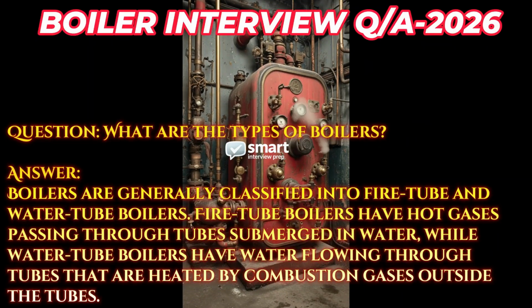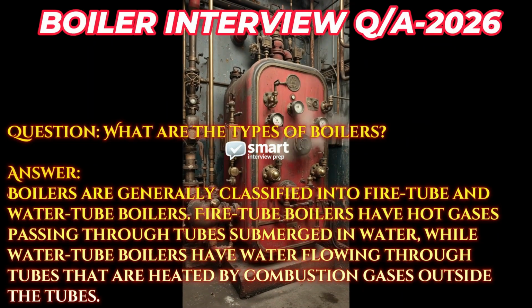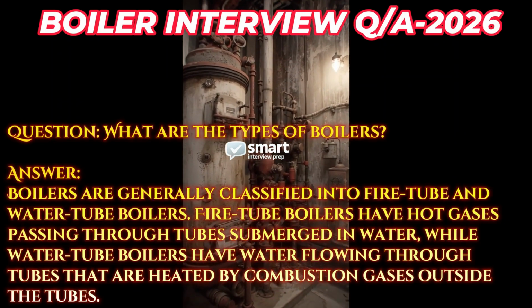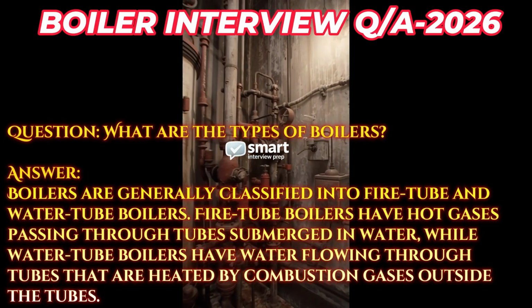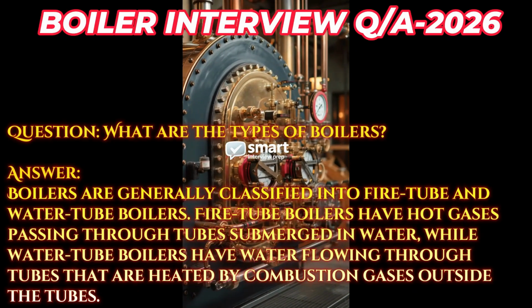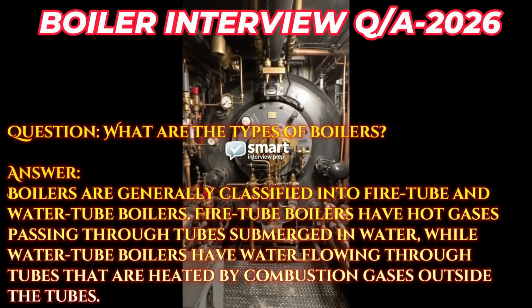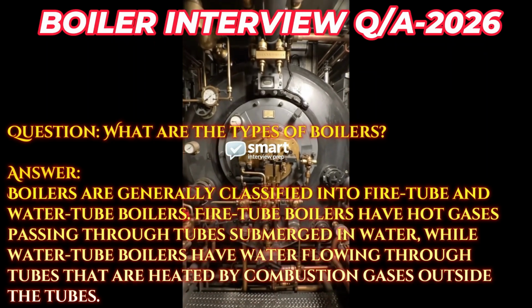Question: what are the types of boilers? Answer: boilers are generally classified into fire tube and water tube boilers. Fire tube boilers have hot gases passing through tubes submerged in water, while water tube boilers have water flowing through tubes that are heated by combustion gases outside the tubes.